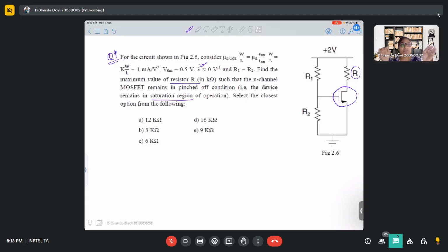In that case, rather than collecting your electrons at the drain terminal, it will start pushing your charges, so you will not see the flow of current that you want from your device. That's why it is necessary for one junction to be forward biased and the other junction to be reverse biased, so that your charges can flow in the path that you create. Is this clear?